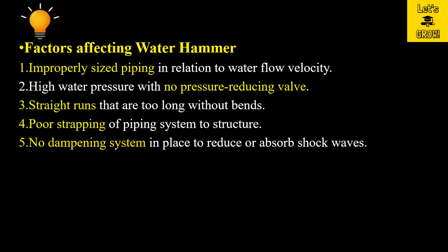Straight runs that are too long without bends. If the pipes are laid in a straight run which is very long, then the water hammer effect will be much more severe. Correct? Why? Because the shock wave produced by the water hammer will travel a long length, and the effect on the pipe can be seen in the longer run. But on the other hand, if the pipe has some bends, then due to the bends, the effect of that shock wave, or the velocity of that shock wave, will be reduced.